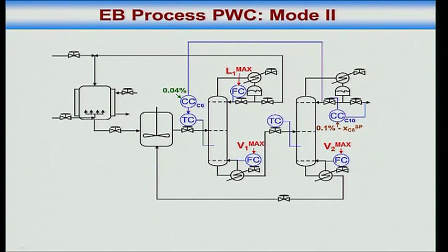This temperature set point is adjusted to maintain the benzene impurity in the product at 0.04%, which my optimizer gave me. So why is it linked to reflux? The reflux is the product. Distillate and reflux is the same, right? It's just ease of drawing. That's all.